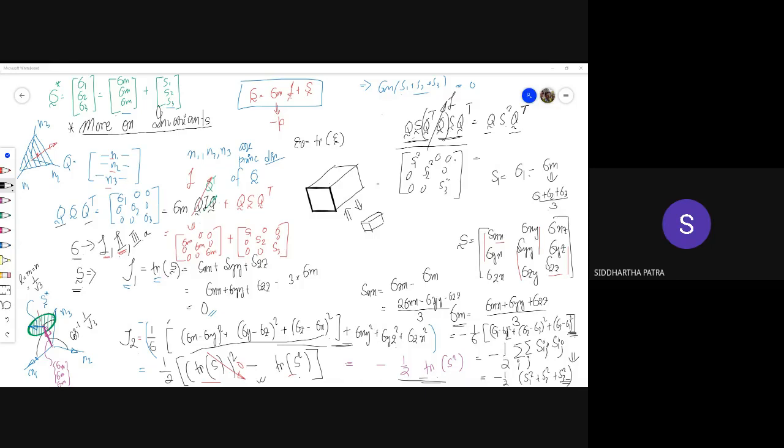So instead, what we are doing is we are taking everything into the principal coordinate system. Okay, and which is basically looking at the stress from a different coordinate system. So axes are at a different angle with the global Cartesian. But there is one principal direction, or more than one principal direction, from which if I look at the stress tensor, it looks diagonal. So essentially I can represent that as a vector, and being able to represent that as a vector allows me to visualize the stress.